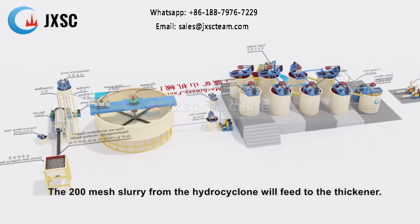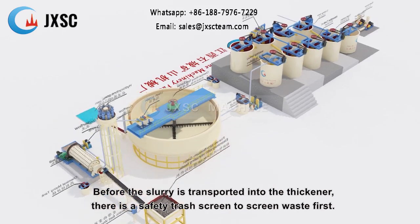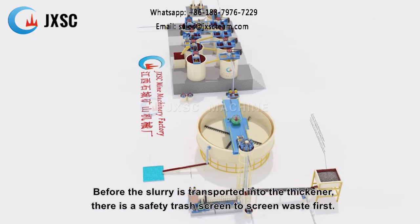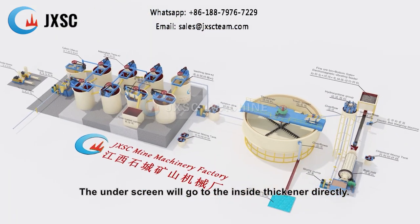3. Pre-treatment before leaching. The 200 mesh slurry from the hydrocyclone will feed to the thickener. Before the slurry is transported into the thickener, there is a safety trash screen to screen waste first. The underscreen will go to the thickener directly.